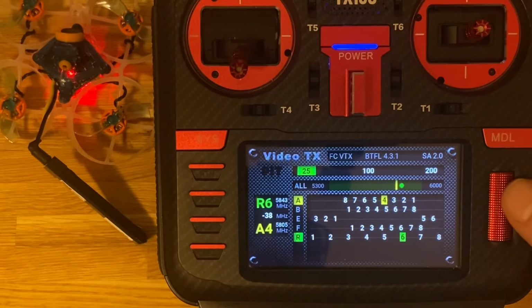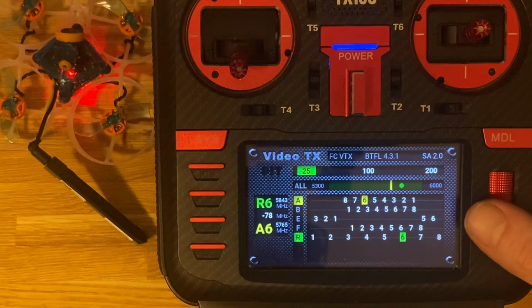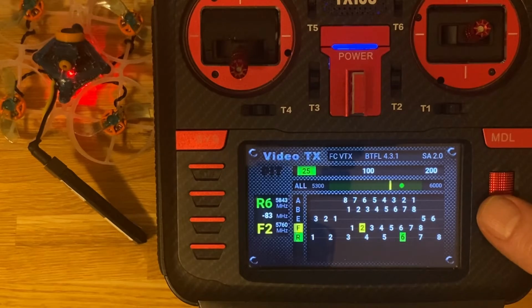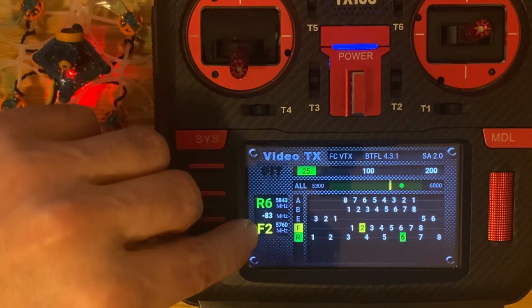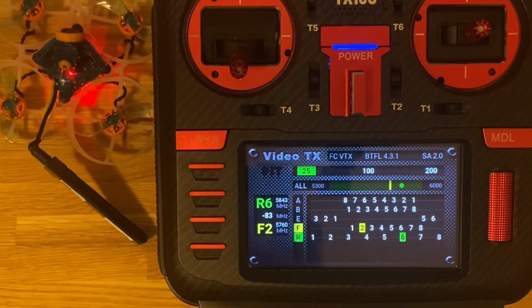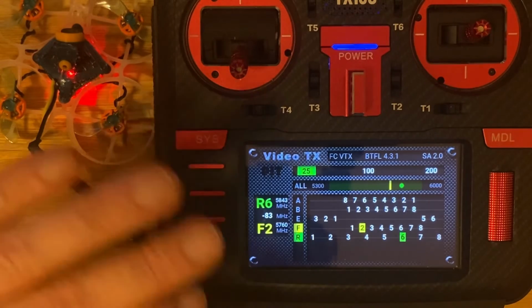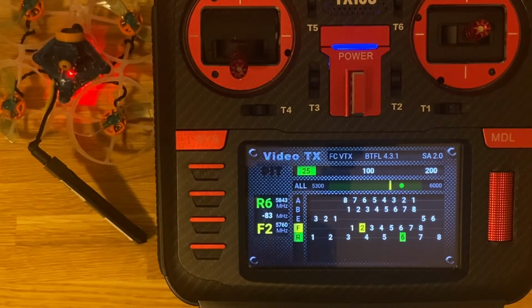You can see where you are positioned, like this green dot is currently selected, and this yellow marker is the new position in the whole band. Here is the currently selected channel and the new one we want to select, and here is the difference in megahertz between those two. So you can see around 20 is the minimum, so as not to interfere with someone else, right?